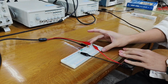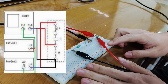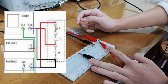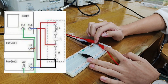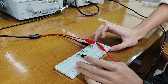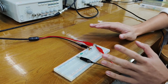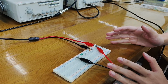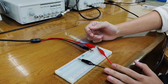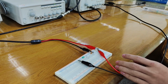Okay, so the circuit for the bandpass circuit is like this, with the second function generator connecting the whole circuit and channel 2 of the oscilloscope across the resistor, just like the high-pass one. And this one is an inductor. This circuit is a combination of high-pass and low-pass, just like we can choose a certain frequency that could pass through. And we can change these three electronic components to have various certain frequencies that could be displayed on the oscilloscope.